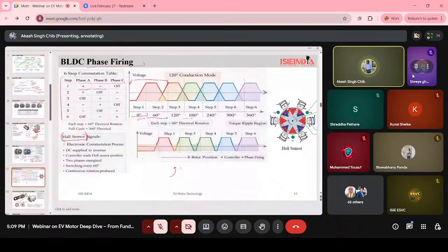You have learned about the vehicle control unit in the powertrain architecture. Then there is an inverter there that does the DC to 3-phase AC supply. This Hall sensor tells the controller which phase to energize, and at that time the rotor tries to move forward. When phase A gets on, the rotor magnet will try to move forward.